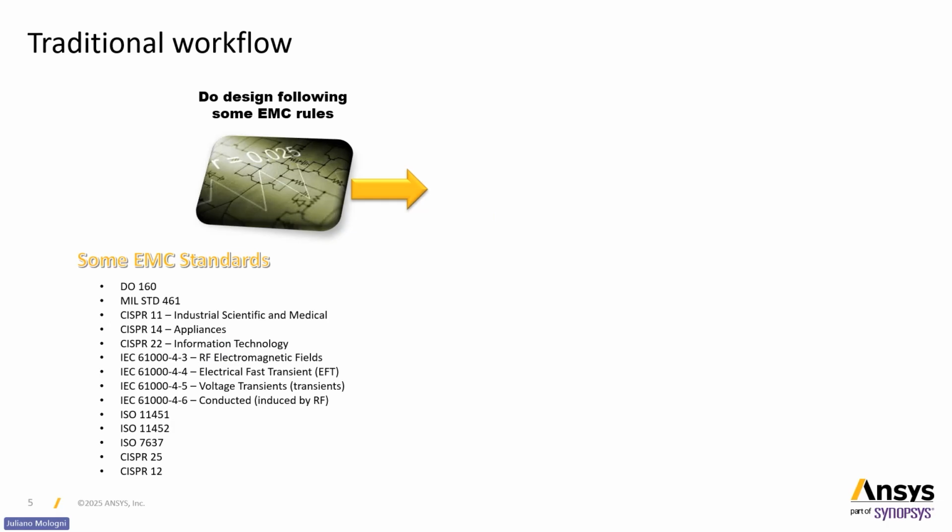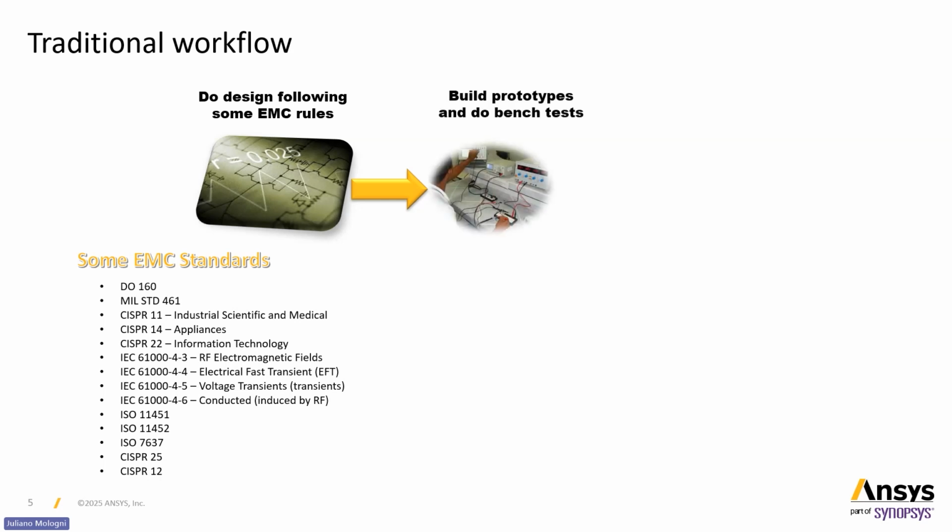I've been working with EMI/EMC for more than 2 decades now, and most of my time I've been working in the lab, and more recently with more focus on simulation. And whenever we are seeing someone that is having some EMI, EMC issues, they explain the workflow that they have in their company. Usually you have someone who knows to design hardware really well. They know all the EMC rules, right? So usually, they create a pre-circuit board with the correct stack up. They make sure you don't have traces crossing a slot in a reference plane. You don't have signals changing reference planes.